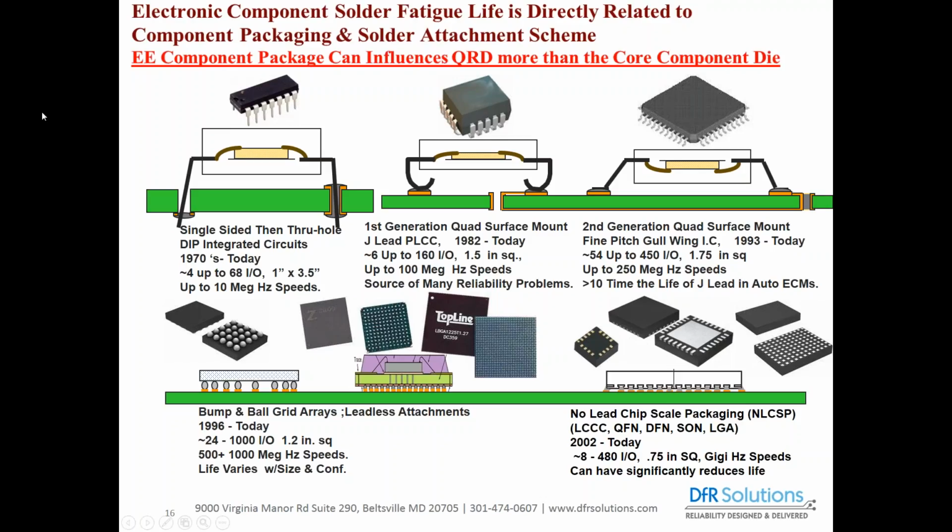Now, as electronics got more complex and we needed more circuit connections, we had to go to more expensive circuit boards with double-sided circuit features on both sides of the board. The circuit features were attached by a copper-plated through-hole known as a via, because the electrical circuits would get from the top side of the board to the bottom side, or vice versa, via that plated through-hole connection.